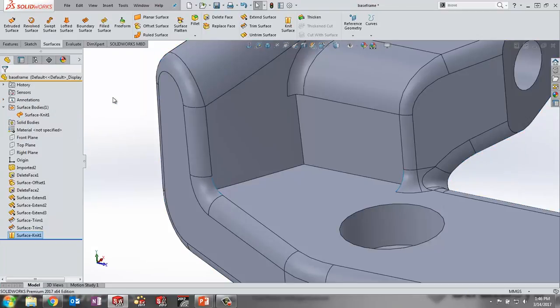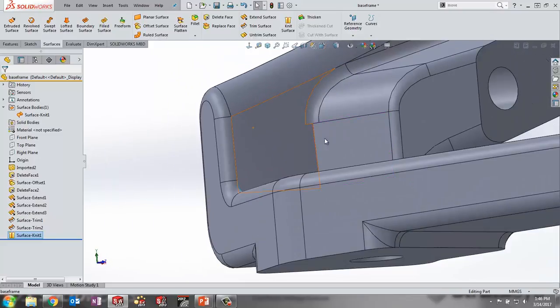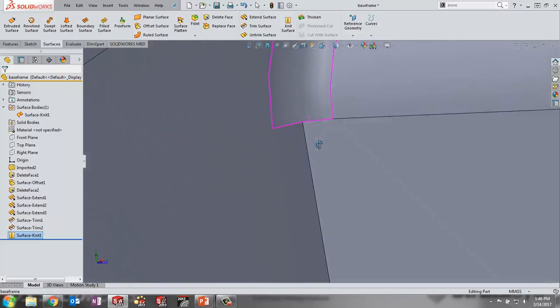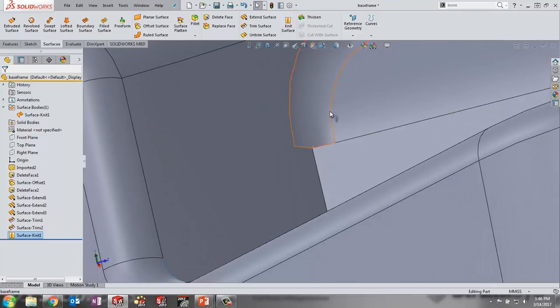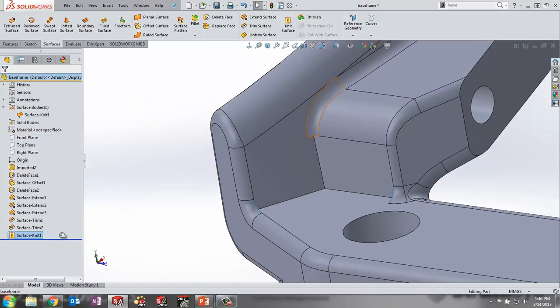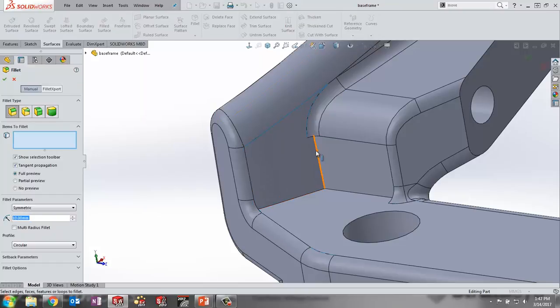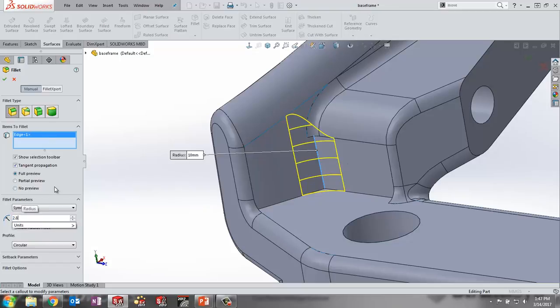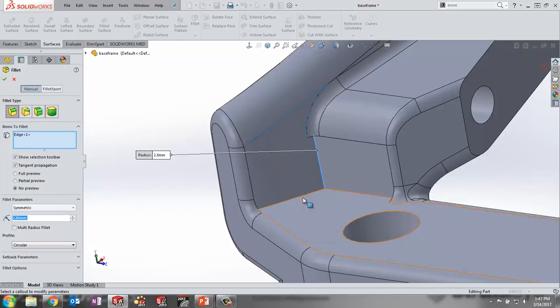You can see that it goes through, and we've created some geometry from that. So you can see we're missing a fillet that we have here, so we might need to roll back in time a little bit. So let me just roll back here. And let's go in, throw in some fillets in here. So we're going to do 2.8. Whoops, sorry, my bad.